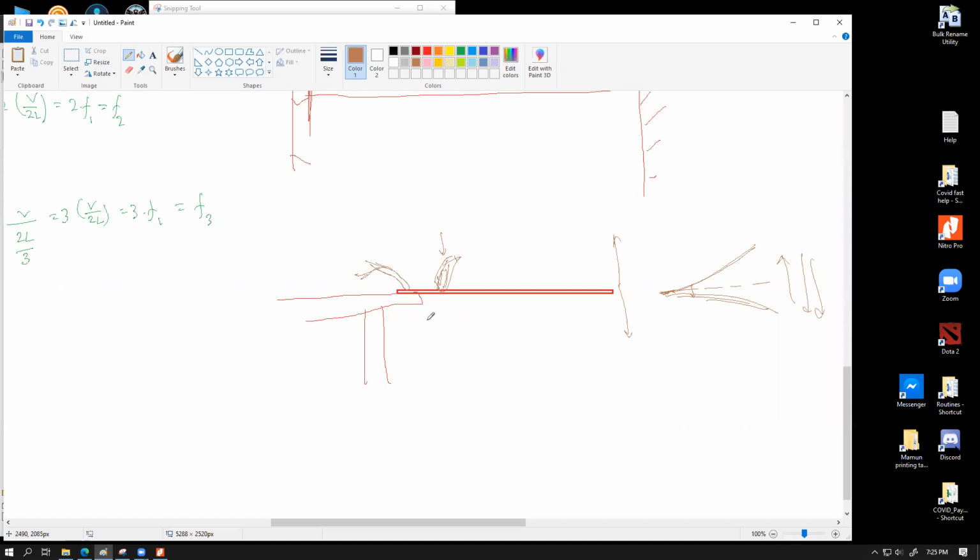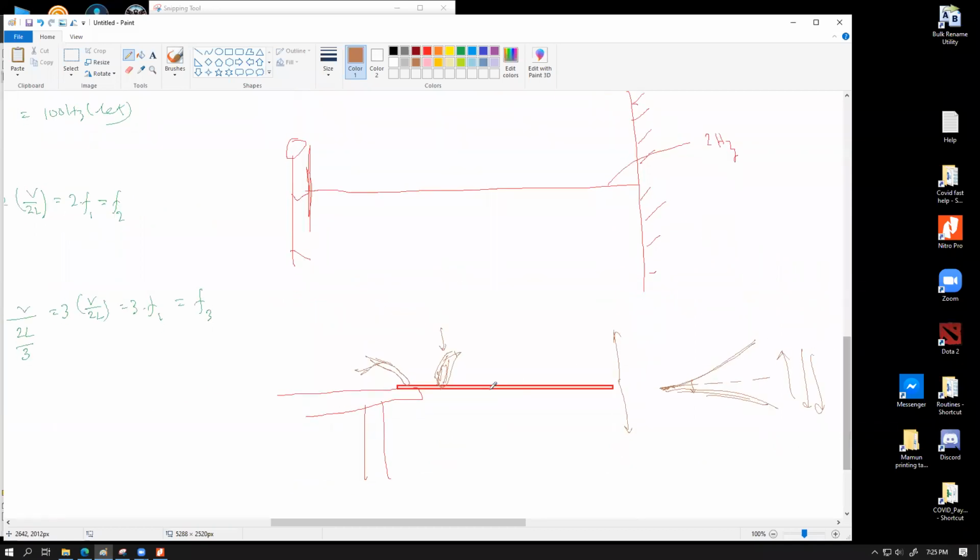Now, why am I telling you this? What is happening here is that at every half cycle of the movement, we are continuously adding a small amount of energy to the system, and that energy addition gives it a really high amplitude. If this ruler has a frequency of exactly 2 hertz, our finger also has to move at 2 hertz. Our applied force should also be 2 hertz.